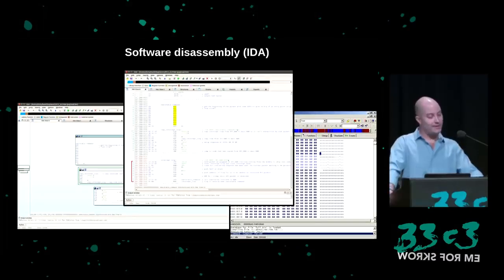With the ROM contents extracted, the software can be disassembled and analyzed. The first step was to identify the CPU architecture. Studying the binary dump, it appeared to be an 8-bit CPU, but wasn't 8051 or 6805 or any of the processor types I tried first. Eventually, I tried disassembling in 6502 and the code made sense.